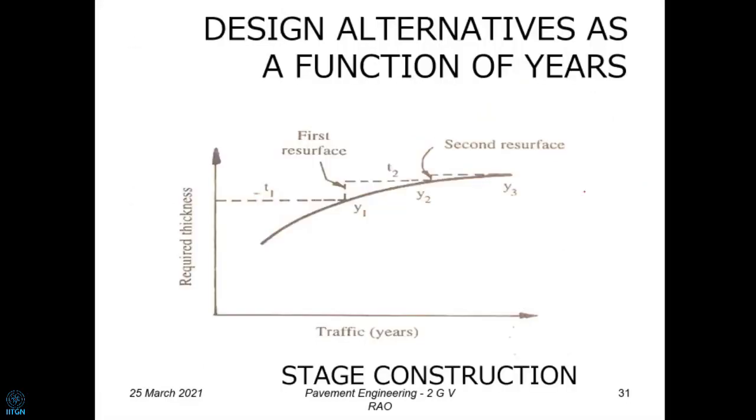Which one are we going to choose now? Are we going to choose the average area? Are we going to choose this area? Are we going to choose this area? So you always find that actually when the contact area is less, contact area less means the pressure is going to be more. So we normally make an assumption that the tire pressure is equivalent to contact pressure. This is just to show that it is not equivalent. Okay, you should remember that as we go further.